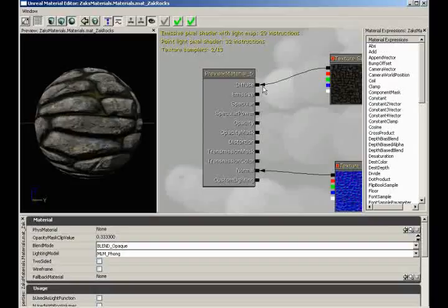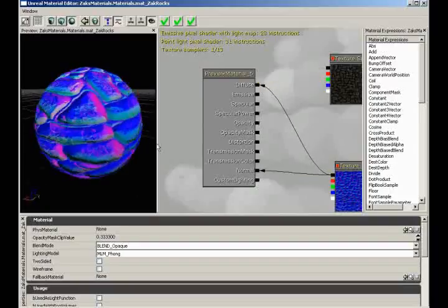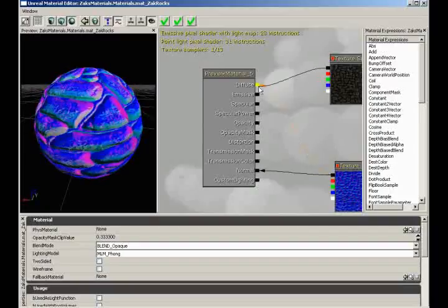In general, you're going to be creating a very large network of expressions and taking that network, tapering it down to a single material, which will plug into one of these channels. Each one of these channels can only have one incoming input. Only one. You can't take like the normal map and also plug it into diffuse. Nope, it'll replace it. That's right, because it ends up replacing it. So keep that sort of thing in mind.